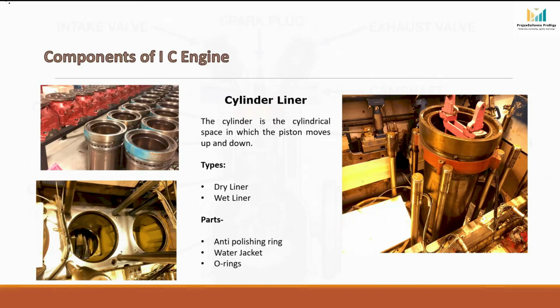However, there is one disadvantage. If the sealing rings or O-rings fail, cooling water can leak and mix with the lube oil, which may cause serious engine problems. That is why the condition of liner sealing rings is very important in wet liner engines.